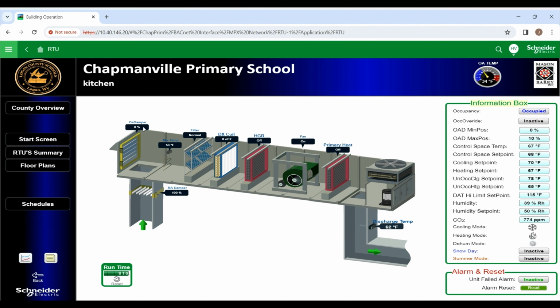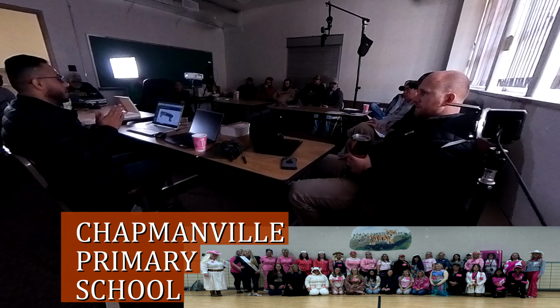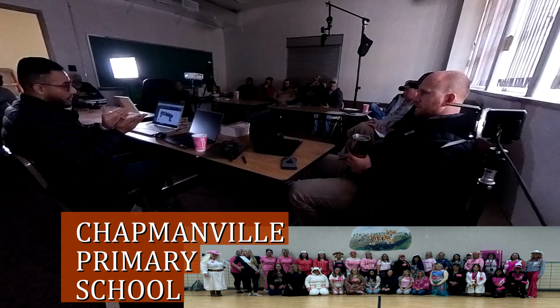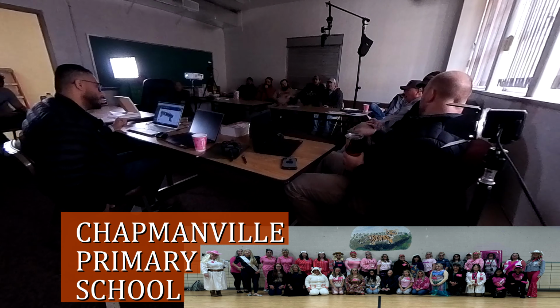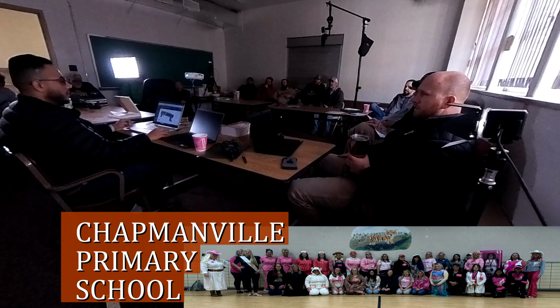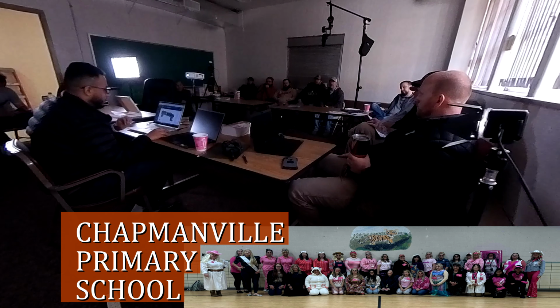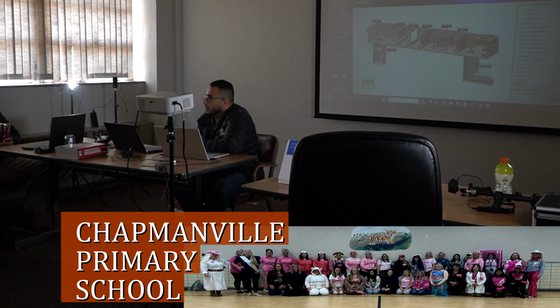So do those have a speed drive on them? No, no speed drive. Or a DC motor? It's an ECM motor, but you have your high, medium, low. Okay. Those are all direct drive too. Yes, every one. Cooling is going to run high, heating is going to run low. It's depending on what is called for. Is it calling for heat, which has a certain speed, or cooling, which will be a certain speed. On the fan only, I think it's the lower speed that you'll have.